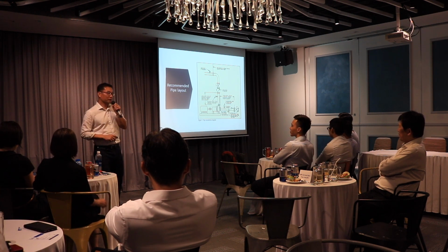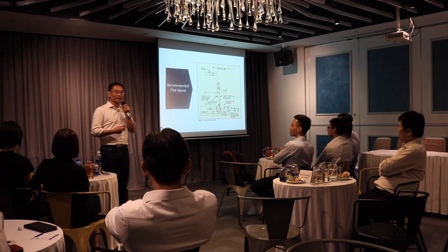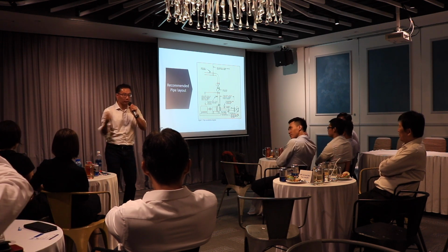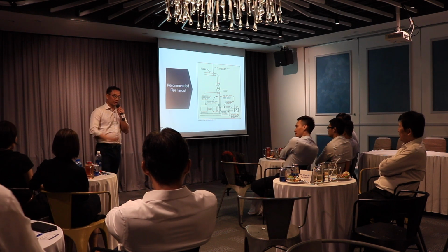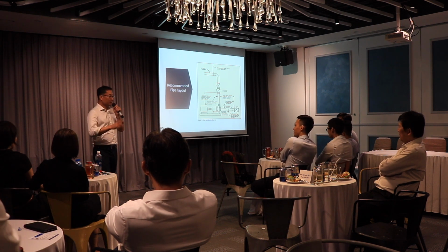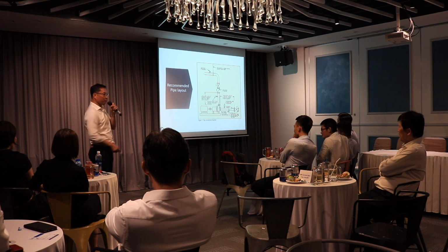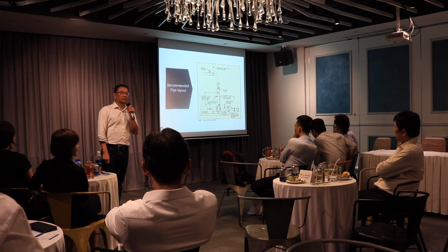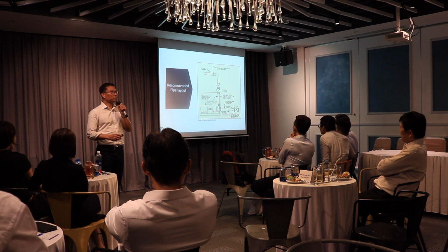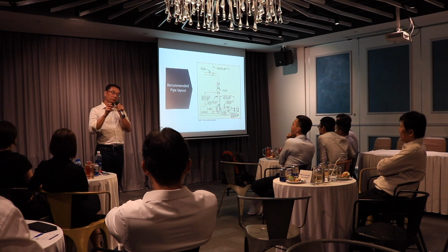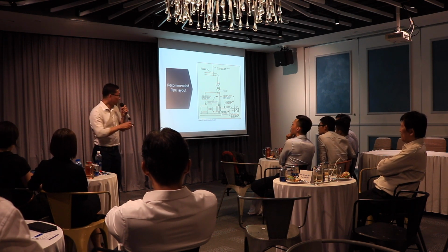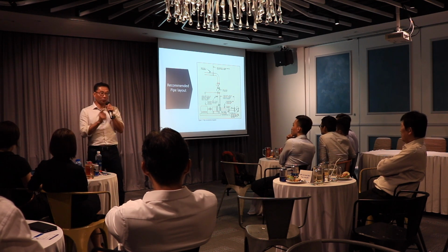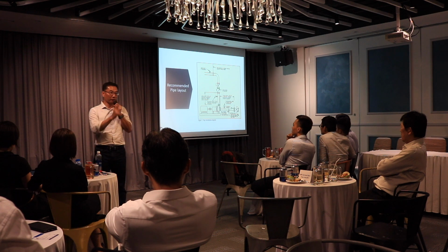I said, Mr. Chia, can you tell me? No, he said, no, tell me how you got it. Oh, of course, take out the pump and measure. Oh, you stupid young man. I just turn off the discharge valve, look at the pressure gauge, the pressure, look at the curve, I know the impeller already. So for any site, if you think you want to save $100 on a pressure gauge, let me advise you, don't save on the pressure gauge. You will save your life.